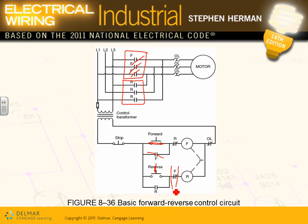Okay, so you can see there are two contactors. The F coil drives the F, the R coil drives the R. The overload, guys, is here. These overloads drive this contact. Any comments, guys, any questions? To stop the motor, you need the button to be right here so you can stop the motor regardless of whether the motor is going forward or reverse.